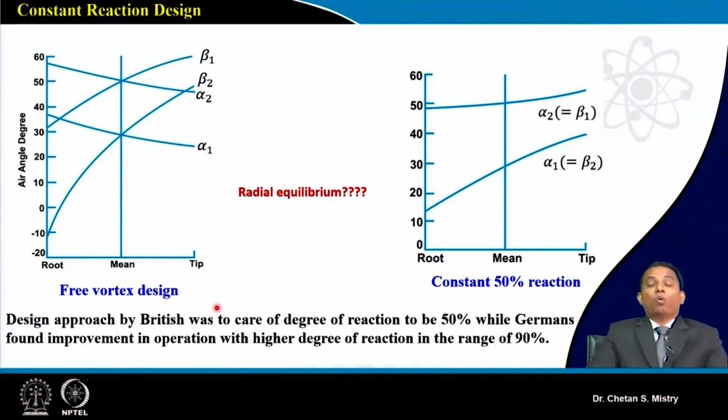So we will be having a whole lot of diffusion, and that will be happening only in the rotor, and my stator will be guiding the flow. So this is a challenge. Now I'm sure you must be realizing the importance of calculating degree of reaction.